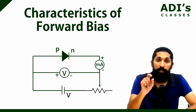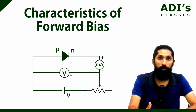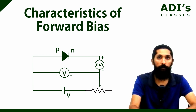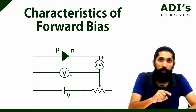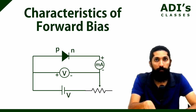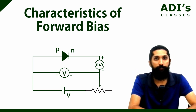You start increasing the voltage bit by bit: 0.2, 0.3, 0.4, 0.5, like this keeps on changing. Now what we observe is that the more voltage we give, the more the forward current is going to be. Basically the current detected by the milliammeter is going to be more and more. Gradually it keeps on increasing.